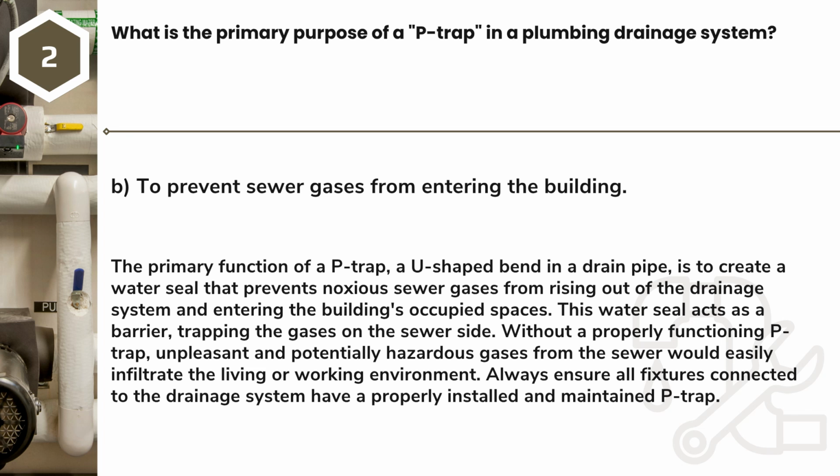Without a properly functioning P-trap, unpleasant and potentially hazardous gases from the sewer would easily infiltrate the living or working environment. Always ensure all fixtures connected to the drainage system have a properly installed and maintained P-trap.